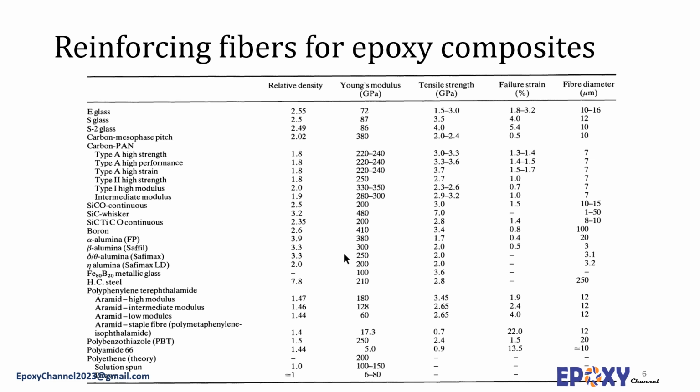The most important fibers are those based on E-glass, carbon, and aramid fibers, and are available in various forms and with a wide range of properties. Glass fiber composites are the most common type. However, graphite, aramid, and other reinforcements might be used for special applications, for example, aerospace and in premium sporting equipment such as fishing rods, tennis rackets, and golf clubs.